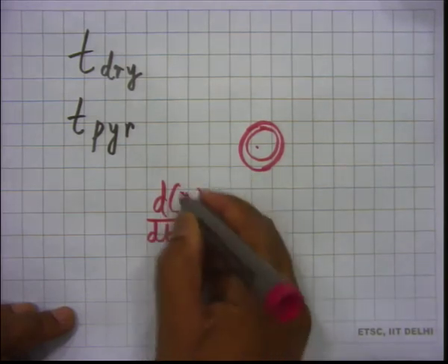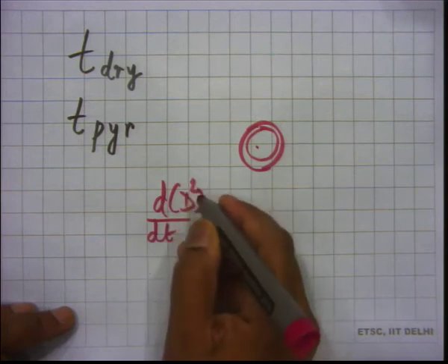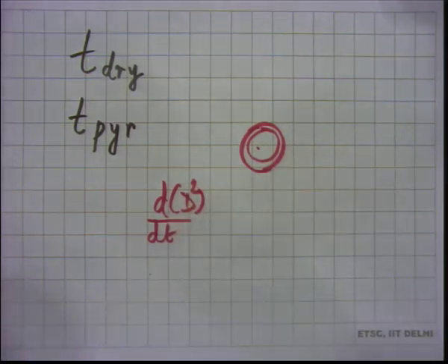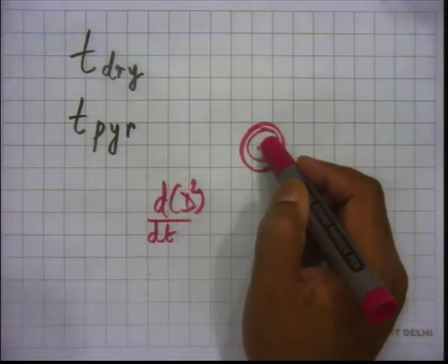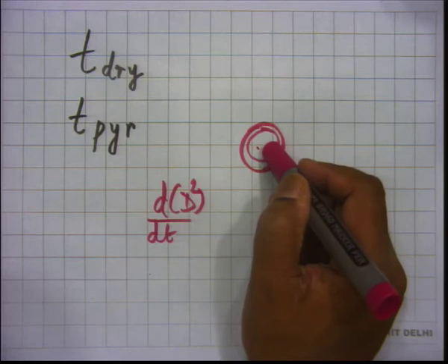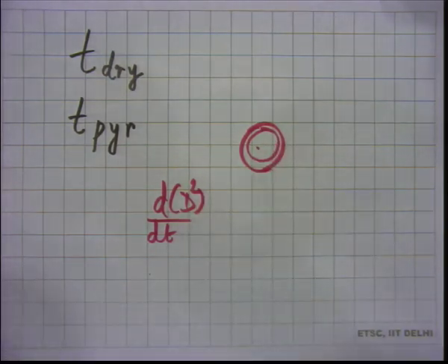In fact, we calculated d/dt of d squared, but we can do d/dt of diameter. So the diameter is actually changing. For a droplet we call it a surface regression rate. So it is spherical and it is reducing. Usually there is not much complication, in the sense that we can say that gases are not getting dissolved in the liquid. We made that approximation, and we didn't have to bother too much about what is happening inside the droplet.